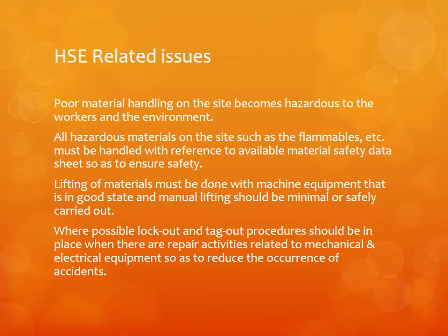Now, poor material handling on the site becomes hazardous to the workers and the environment. All hazardous materials on the site, such as flammables, etc., must be handled with reference to available material safety data sheets. Lifting of materials must be done with machine equipment that is in good state, and manual lifting should be minimal or safely carried out. Where possible, lockout and tagout.